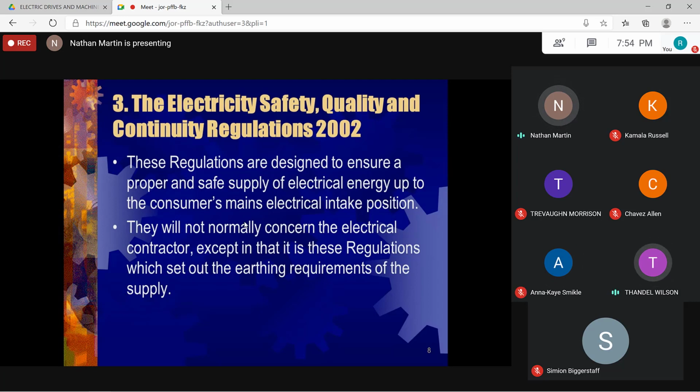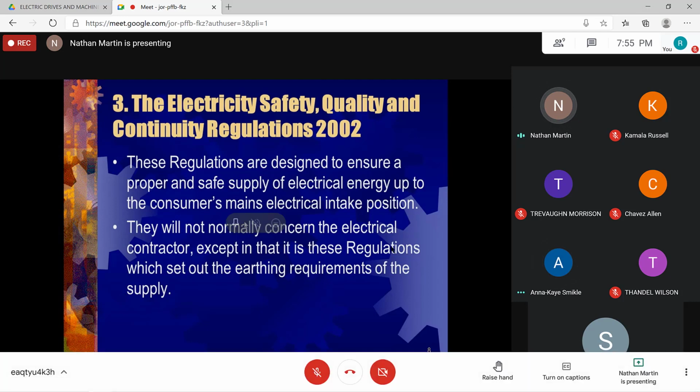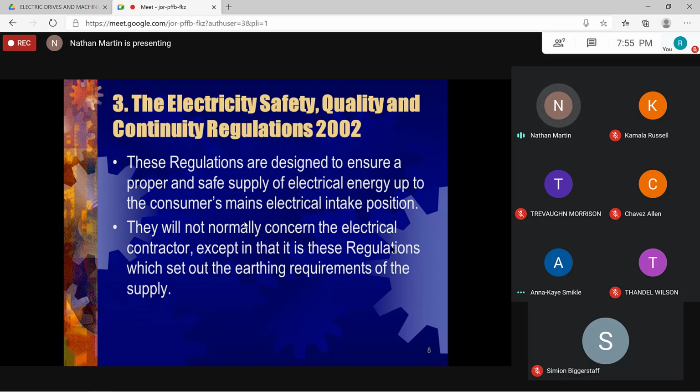Electrical fire is one of the hardest fires to put out, right? Yes, if the breakers don't trip, what will happen is that you're going to have a circulating current, and that circulating current causes anything it's circulating through to overheat. And when things overheat, you're going to have heat being generated, right?